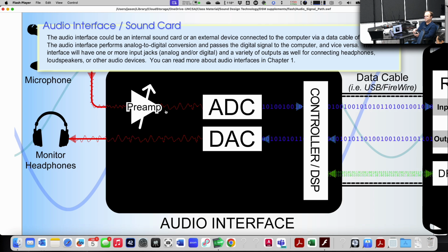So this is balanced audio coming in and out. And balanced audio is way better at sending signals a long distance without getting noise in them. But it also has a really high quality headphone output that's on a 1/4 inch connector. It's going to be a lot lower noise and much higher quality.